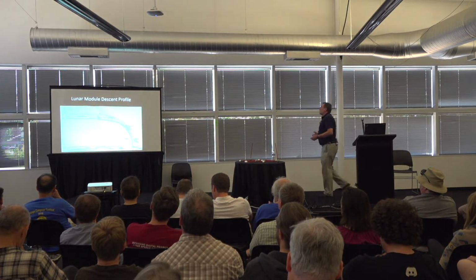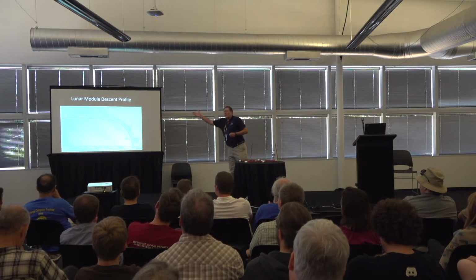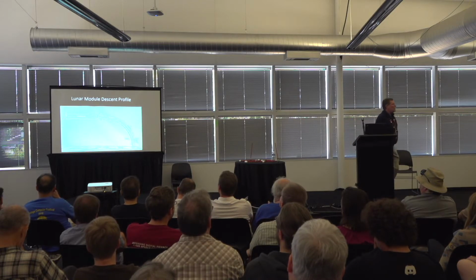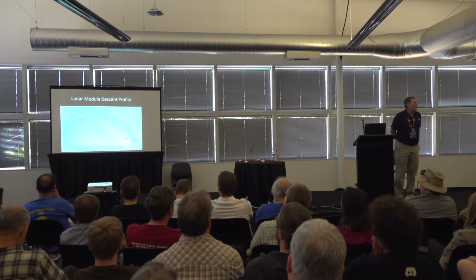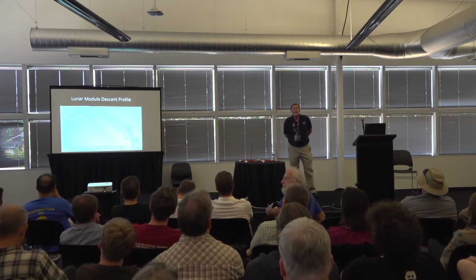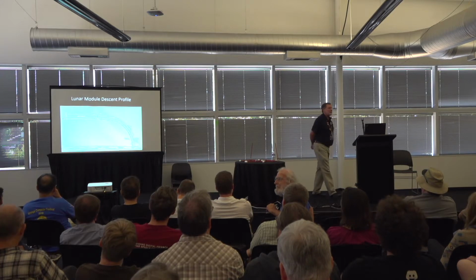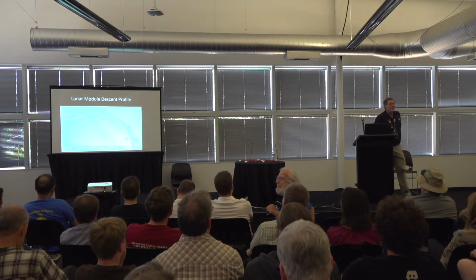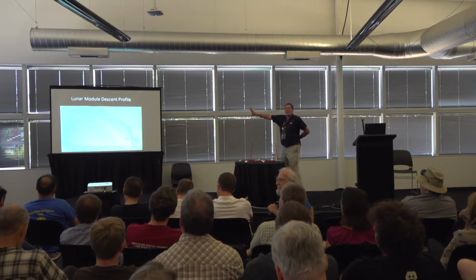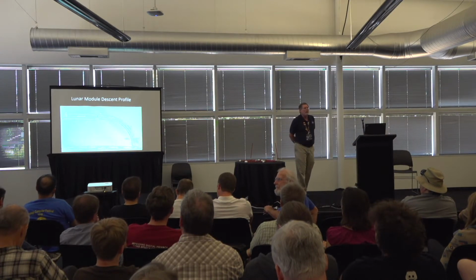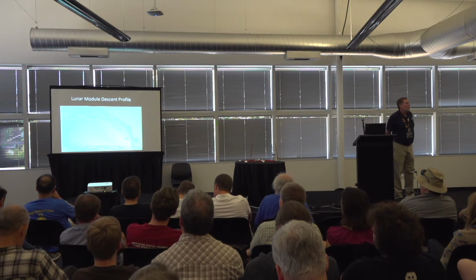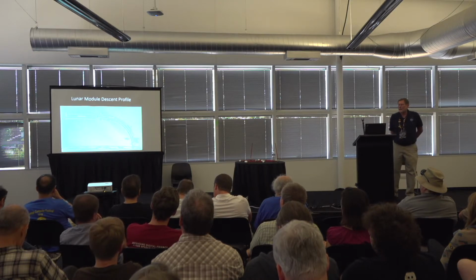This is the schematic view of it. Again, he brought up all that stuff. You fire up the landing program, P63, about 10-15 minutes beforehand, sometimes 20. It actually does all the guidance calculations. It does take a while. So it's not like you press a button that says land on the moon and everything hops into place. We have our braking phase, and this really isn't to scale because braking is the vast bulk of the entire landing. We have our approach, where you get your first view of the landing site.